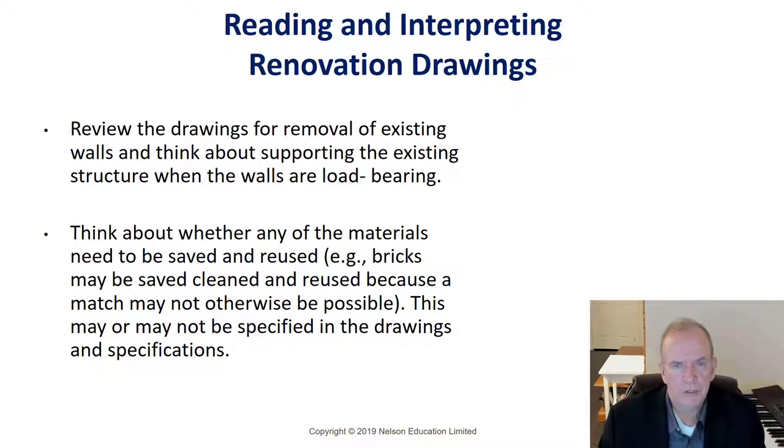But you kind of know if it's a dashed line and it's a wall that it's pointing at, it's saying that, well, it's either hidden or it has to come out. And usually you can figure that much out by looking at it, right? If it's in a floor plan, it's not going to be hidden. So it must mean that it needs to come out. And usually there'll be a leader line pointed towards it and it'll say remove wall. So that clarifies it for you.